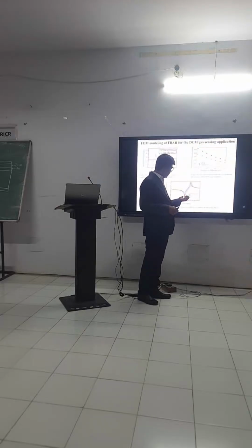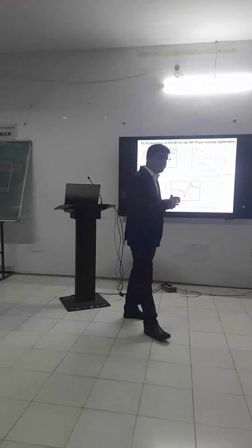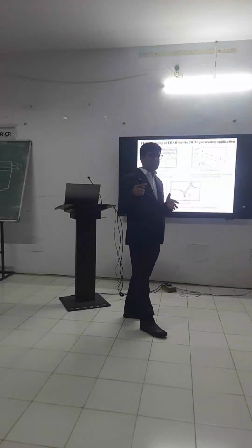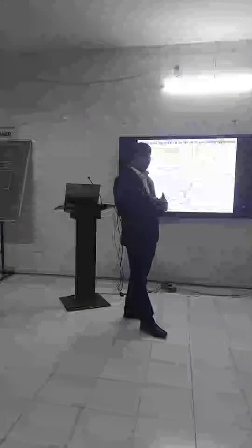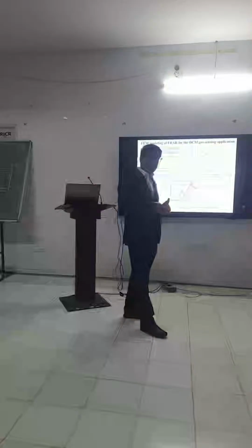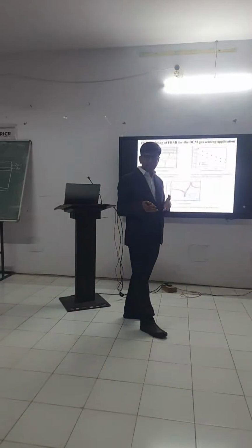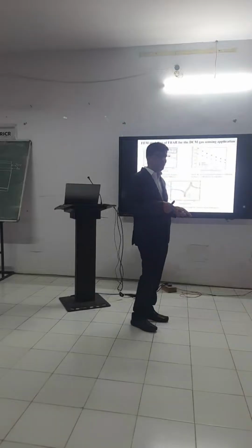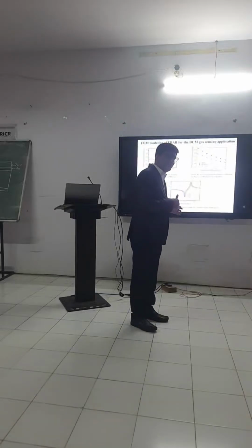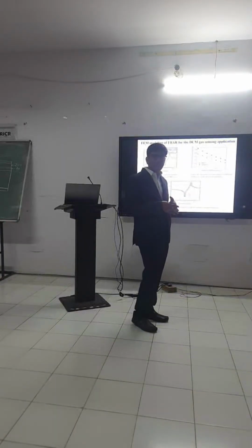Clear? So there is no degradation in your sensor performance, but your frequency will shift a little bit. Why? Because in sensor response, we are interested only in the change in the frequency. Whether it is 2 GHz or 2.2 GHz, it will give me the same response. But it will impact you when you go for filter design. Because in filter design, if you are looking for 2.4 GHz and due to the variation of the mirror layer your frequency changes, then you will not achieve the particular filter you are targeting.